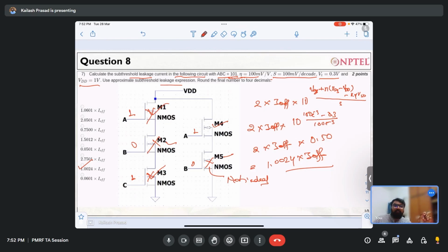But on the alternate side, suppose in the servers, you have continuous power supply, and there you want your server to run at extremely high frequency, say 5 gigahertz. There you will be using low VT transistors. So there you are not concerned with leakage. You are concerned that if you are running a neural network, it should immediately give you the answer. If you're clicking on Google, it should immediately give you the response. That's how it works.